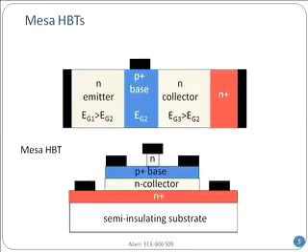Why do you need it? Because semi-insulating material has very low conductance. As a result, because these transistors will be used at extremely high frequency, do you remember in the last class we said that if you have too many junction capacitances, that reduces the FT of the transistor? The junction capacitances must be suppressed. And by using a semi-insulating substrate to begin with, you reduce the capacitance. So therefore, it will go to a very high frequency.